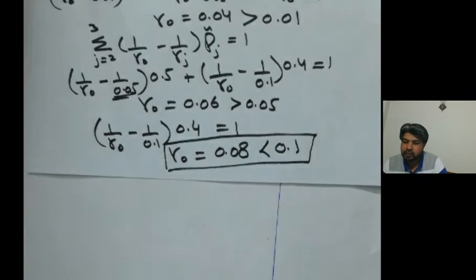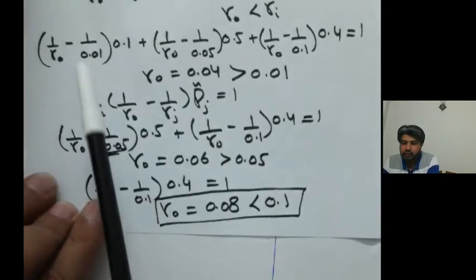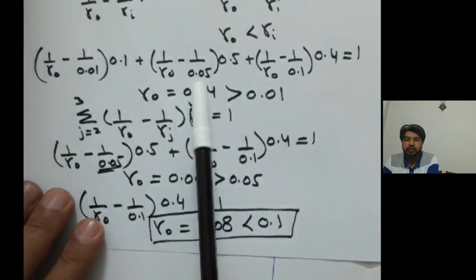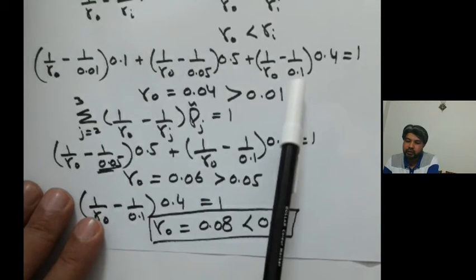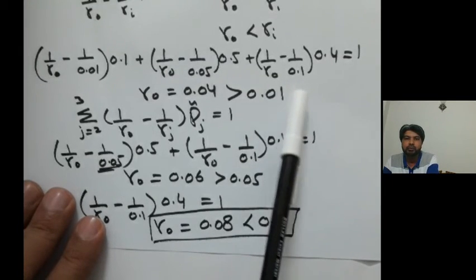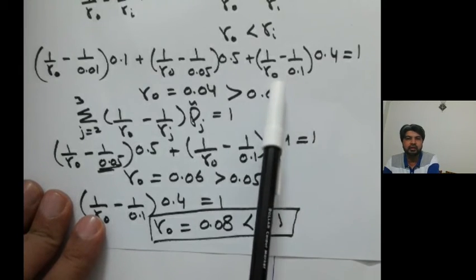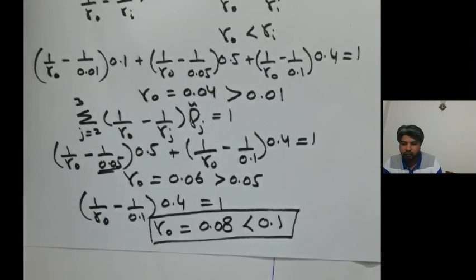So that means you would get an optimal capacity when you would not transmit anything when you are in the state 0.01. You would not transmit anything when you're in the state 0.05. You only transmit when the channel is in the state with a signal to noise ratio of 0.1. And remember, because both the transmitter and the receiver have channel side information, you can adapt with these conditions. So now let's see what would be the capacity.